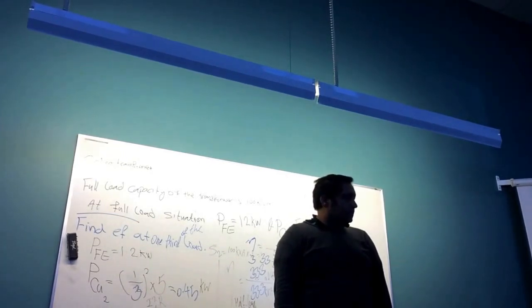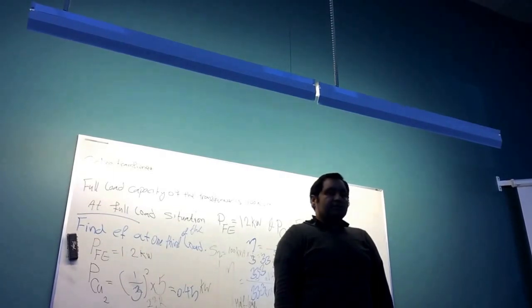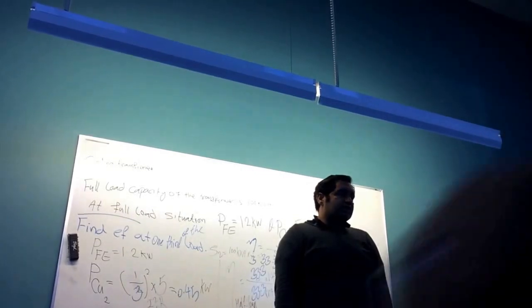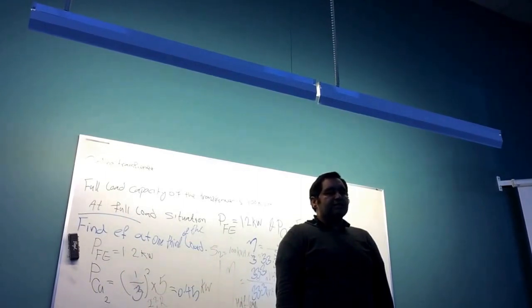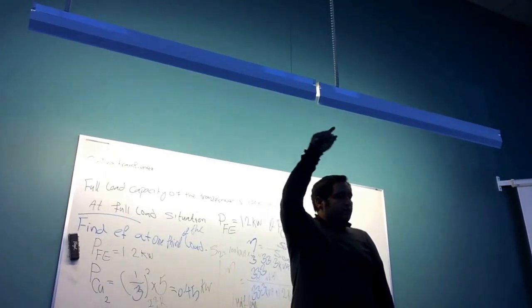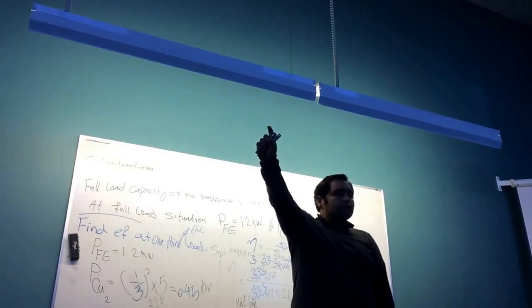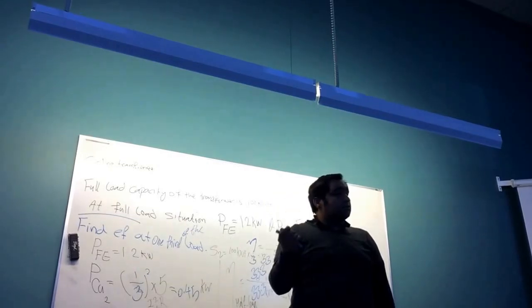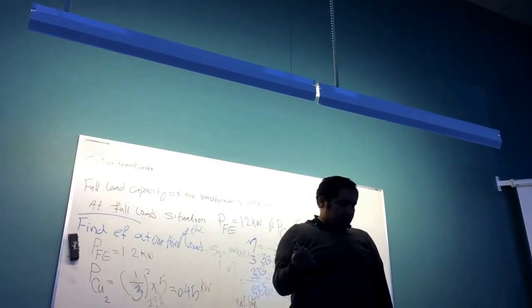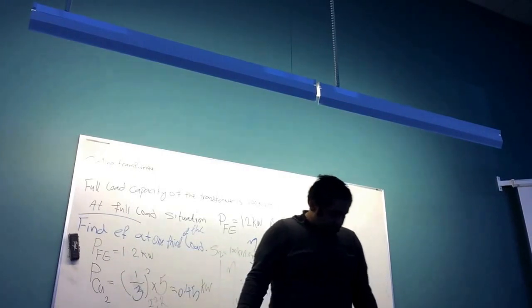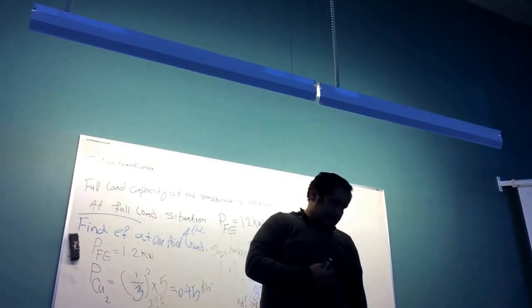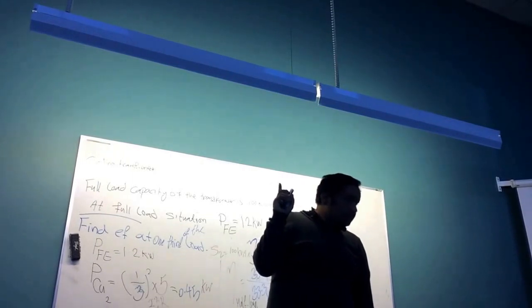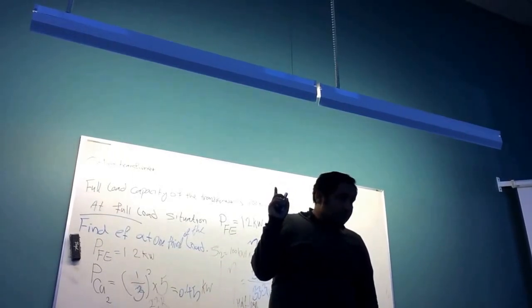It's not a good transformer, right? Because you have a lot of voltage drop in a full load situation. But if your voltage stays at 230, then your voltage regulation is 0%. V no load minus V full load equals 0. 0 over V full load, which is 230, is 0. So that's just the concept of voltage regulation. But let's see if we have a question of maths. Question: voltage regulation, what is it?